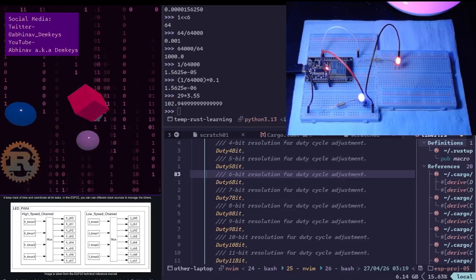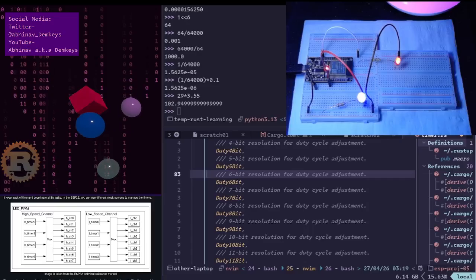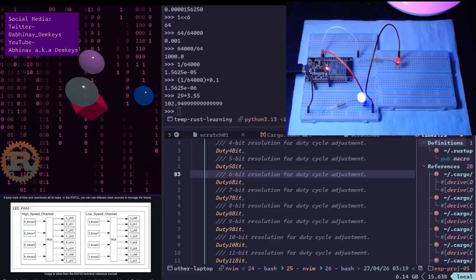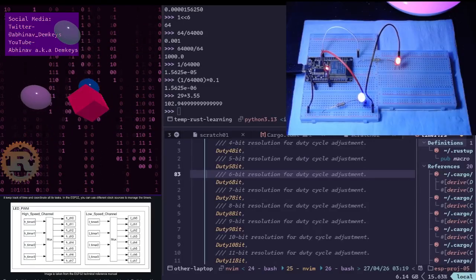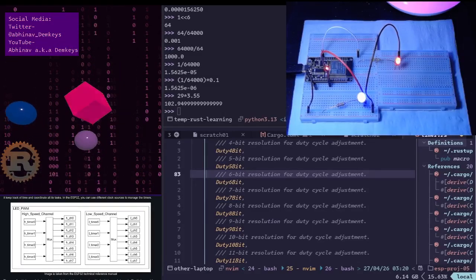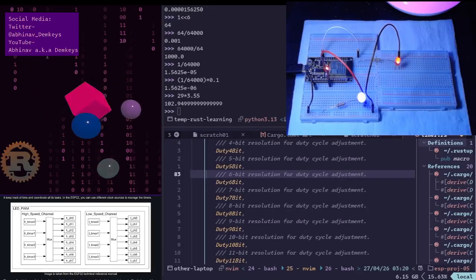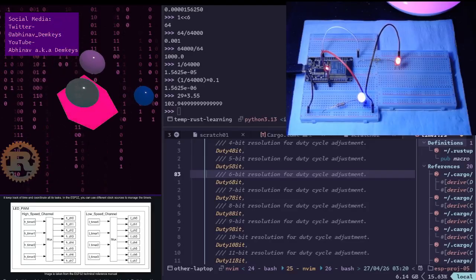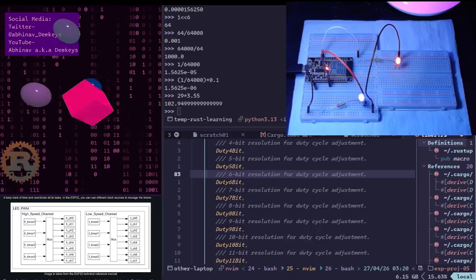You can use it for two things. Well, you can probably use it for multiple things, but two things you can definitely use it for are flashing the program onto the device, and then also debugging the program as it's running on the device. If you buy the chip by itself, you can't just connect it into your computer and flash your binary onto that CH32. It's not going to work, at least for that specific one, the incredibly cheap low power version.